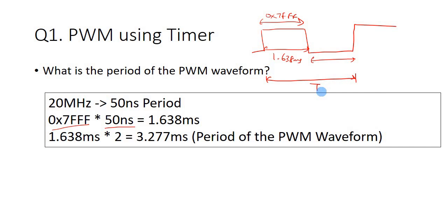Okay, so I think it's quite obvious that the period does not in any way affect the average voltage that the signal will see, because as long as it's 50% PWM, the average voltage will always be half of the voltage for 0 and 1.